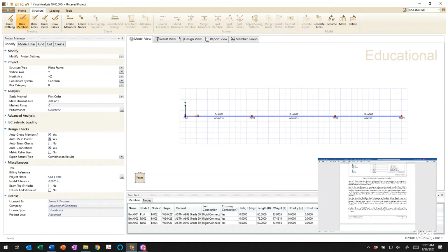Let's see, we'll go to step C. We just did that. All right, step 3, we're going to set the joint restraints. So right now, this beam is just floating around in a hypothetical space. It isn't restrained to the ground at all. So we need to add joint restraints, not to be confused with joint constraints or member releases. These are joint restraints, which are basically the reactions for the beam, reactions for the girder.